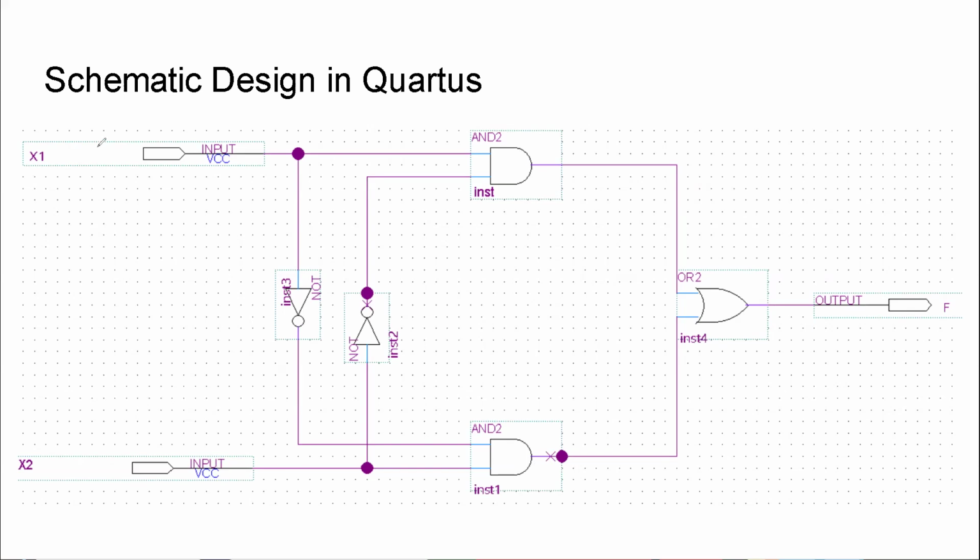So let's start. Let's go with inputs X1 being a 1, or true, and X2 being 0. First, our input X1 is going to go through our NOT gate and be flipped into a 0. And that 0 is going into this AND gate. And our X2, the 0, is going to fall over here. But that 0 is also going to go through its own NOT gate up this path and get flipped into a 1. And the 1 up here is going to be right next to this AND gate.